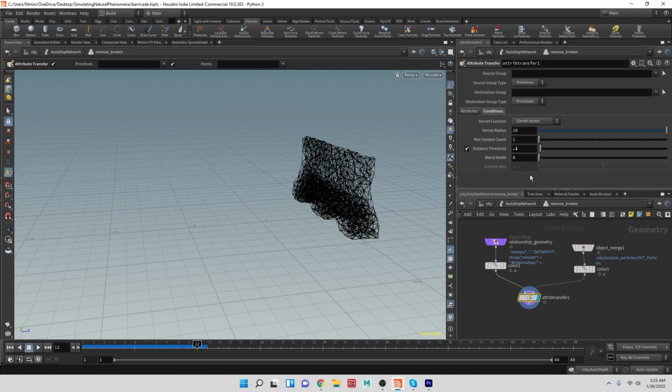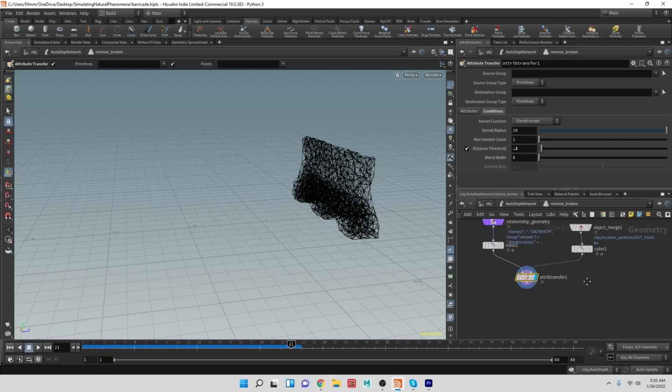So by this point, we should have gotten some points. So I'm going to increase the distance threshold. And then let's recalculate this. There we go. So maybe 0.3 is a little bit much. And put it 0.2. Because we didn't have those replicated points, it needs a little bit of a bigger range because particles die immediately on contact. That looks good there. Okay, so we're getting some hits and the particles changing the color here. I'm going to put it 0.25, kind of in between the last two.